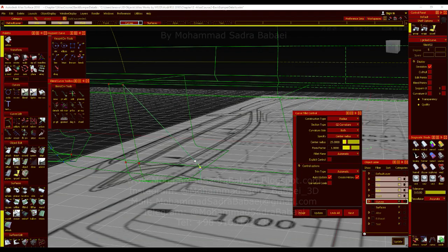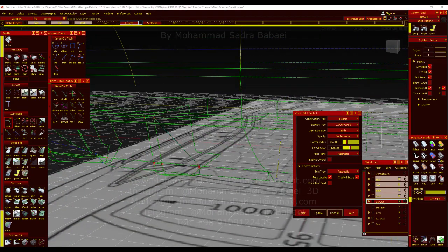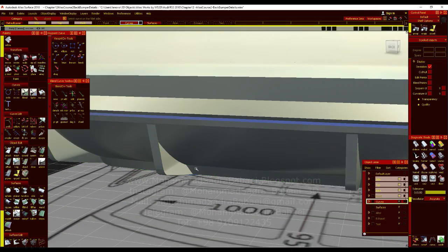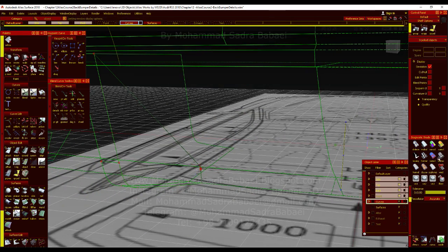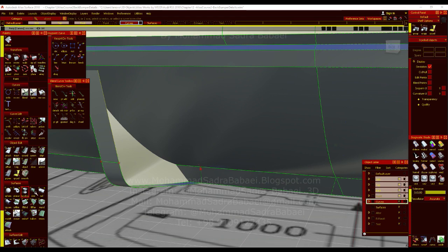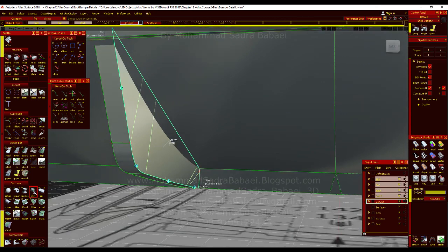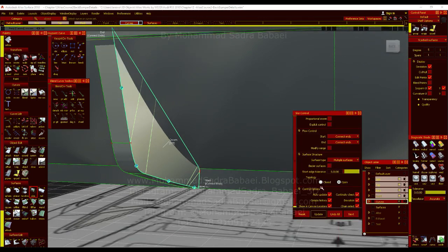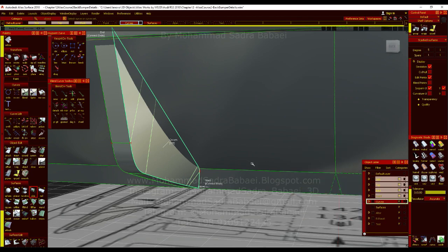Add a fillet between them and connect them. So let me use this skin again. Chain select and this one. Okay, it's done now. A little crown as you want it, and they are connecting positionally, and it's a good